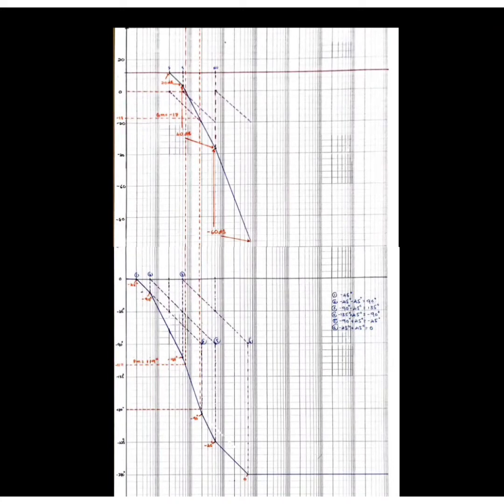To obtain the value of phase margin by using the magnitude graph, draw a horizontal line at 0 dB so that it collides with the magnitude graph. From the point, a straight downward line is drawn and connected to the phase graph so that it collides with the phase graph. At the point of collision, a horizontal line is drawn and the value of the phase margin is obtained, which is negative 119 degrees.